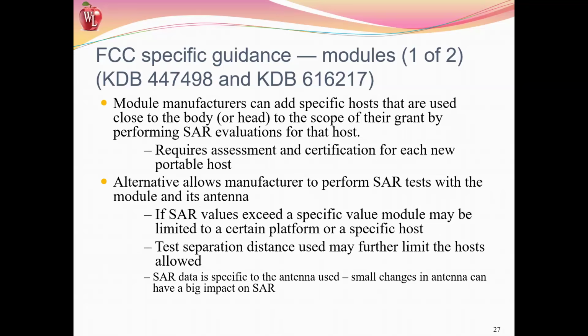A small change in an antenna can have a big change in SAR. And I don't deal as much with modules that have to have SAR, but I deal with the modules that have to have MPE, and you can't change the antennas. The antennas have to be what they were certified with.